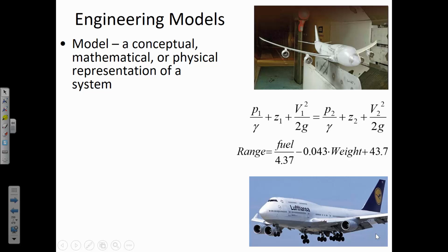The same thing is true of this velocity head term. If you look at velocity squared, then that's meters squared per second squared, and divide it by g, which is meters per second squared, then what's left is meters. So my point is that a fundamental equation is going to have consistent units, whereas an empirical equation, this 4.37 may just be like a unitless conversion factor or some sort of a slope coefficient that we have to just multiply by the data in order to get things to fit, but it's not necessarily based on some observed